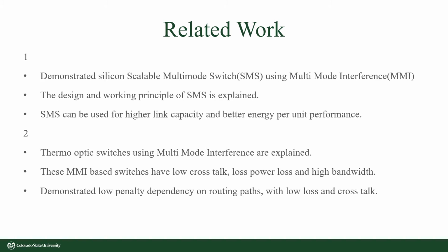In the next paper, I read about the multimode interferometer based thermo-optical switches. Other than the cost, these switches have low crosstalk, low power consumption, low loss, and high bandwidth. This is achieved because the design of the switches uses wavelength division multiplexing, electron beam lithography, and reactive ion etching. The authors also demonstrated the switches with power penalty dependency on the routing paths, with low on-chip loss and low crosstalk.